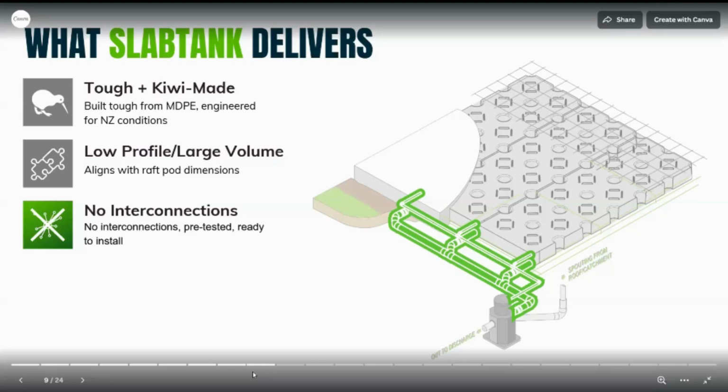Another question here. Is this directly applicable to standard designs in Australia? Are there internal ribs like a typical pod slab, or do the 160 concrete piers replace the internal ribs? That's a great question. And yes, those concrete piers do replace the need for ribs. So they give the slab the bearing down instead of ribs.